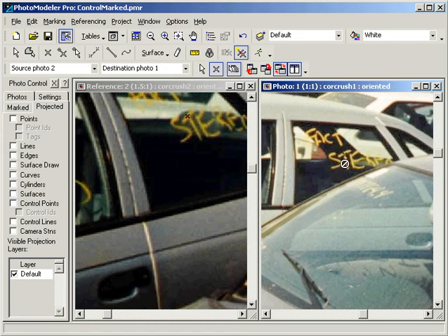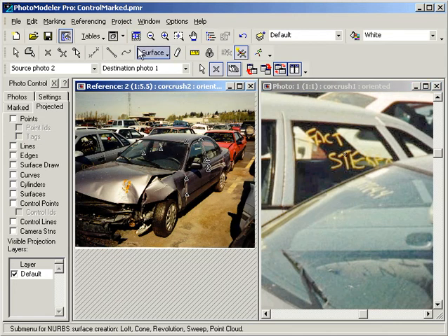We mark the point. You should also be sure that the exemplar vehicle from which you got the control points is the exact same model. It should be the same make, year, and model. Even some of the minor features such as body lines and molding can vary in shape or location in the same models due to dealer options and production variations.